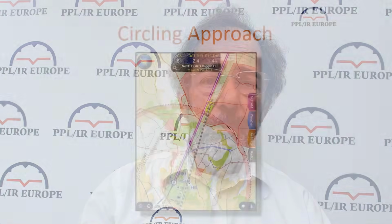Bear in mind, if you're using heading and alt on the flight director, these modes won't be affected by having the HSI set up for a final approach, so you can load the visual approach for the landing runway as soon as you break off the IAP. But if you do that and go around into the missed approach, you will need to reload the original approach in order to activate the missed approach procedure for the original IAP. That's a lot of button presses in a short period when flying low and slow, and can contribute to the difficulties and dangers of a circling approach.